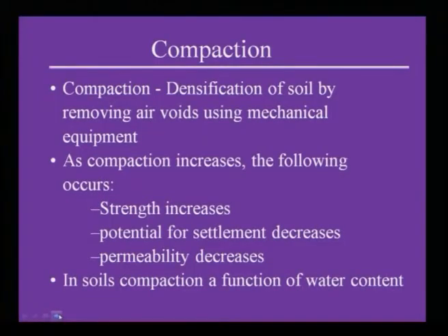Next phase of your laboratory test is your compaction. Compaction is densification of soil by removing air voids by means of mechanical equipment. The difference between compaction and consolidation is that consolidation is expulsion of air plus water. Primarily consolidation is expulsion of water, but in case of compaction it is densification of soil by removing air voids